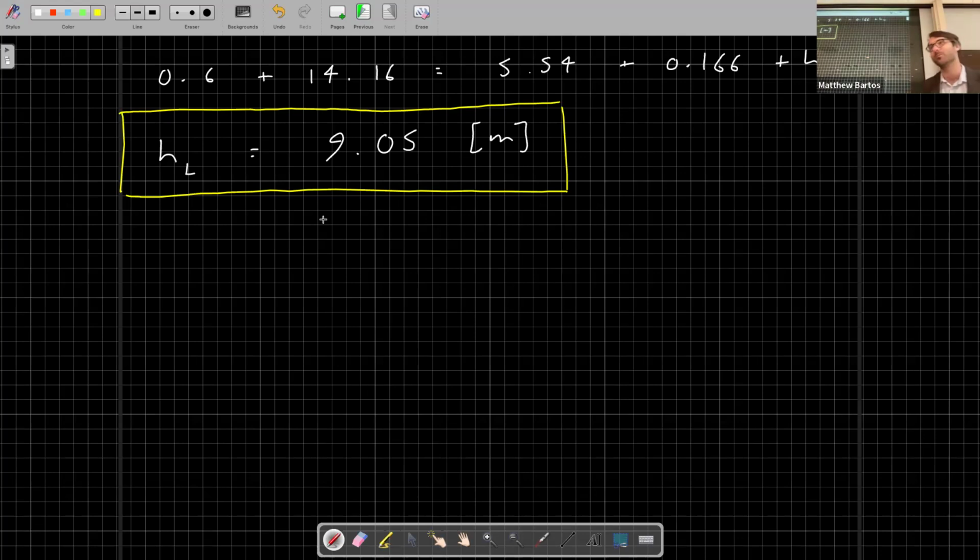Maybe think back to the PowerPoint I showed at the beginning of class. Yeah, you add the sluice gate. A sluice gate. So let's assume that the flow is already supercritical coming in, and we just want to add something to assist with the hydraulic jump. Maybe thinking back to the pictures I was showing earlier today. Yeah, so we can add energy dissipators to try to assist that hydraulic jump.